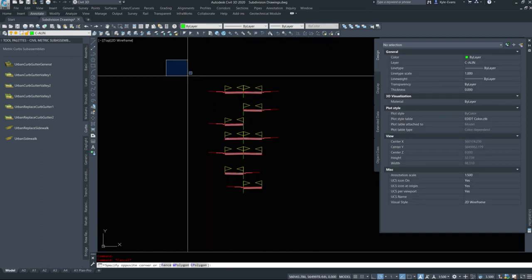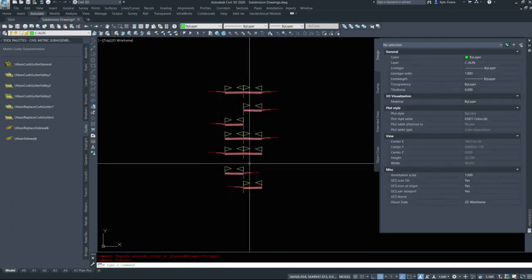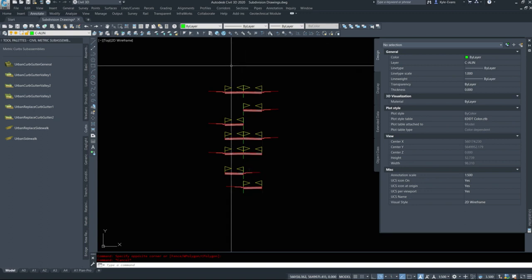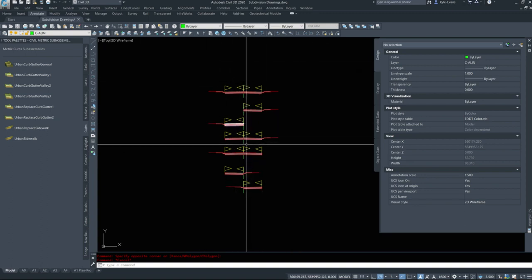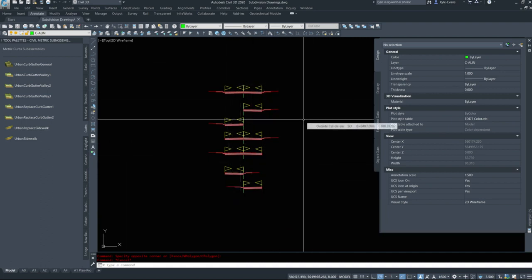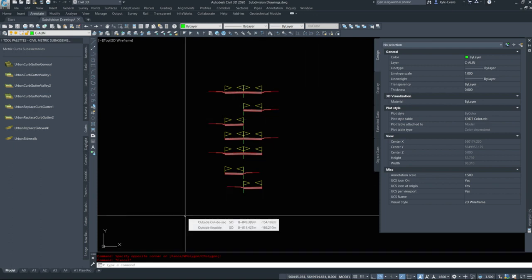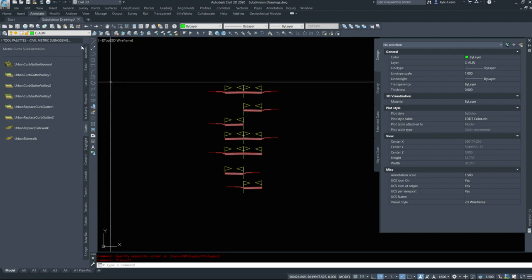So chances are we will not need all these pieces. However, in the past when I've been doing intersection design, we will need an extra one of these assemblies. We'll have to make it on the fly. We might not name it properly. So in order to just save yourself some time, make them now. So I have 7 assemblies. These are probably the 7 we're going to need. Hopefully we don't need any additional ones, but when we get into building the corridor, we will find out.